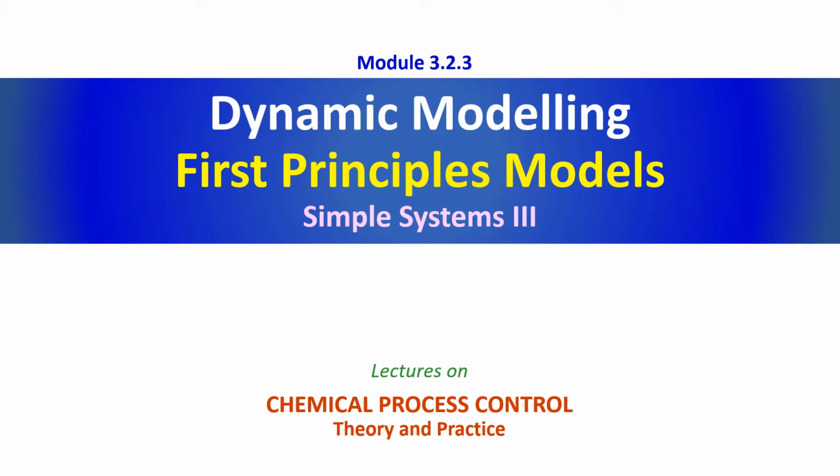In this lecture we will be looking at PI control of the surge tank, temperature control of the surge tank using a PI controller, where the integral time has been taken to be less than the tank residence time tau, and we'll derive analytical expressions for the solution of the governing ordinary differential equations. That's the agenda for this lecture. So let's get going.